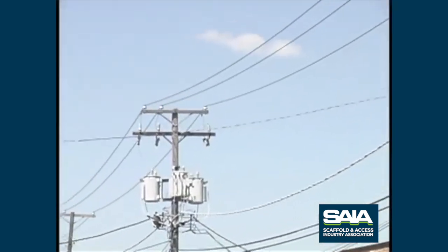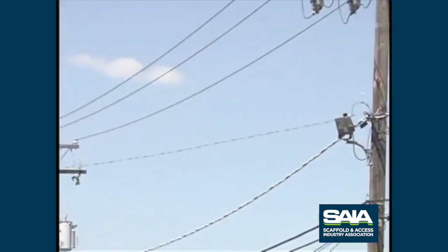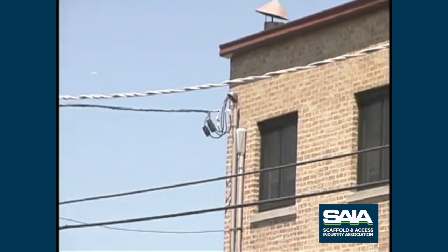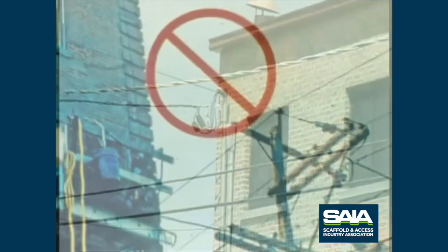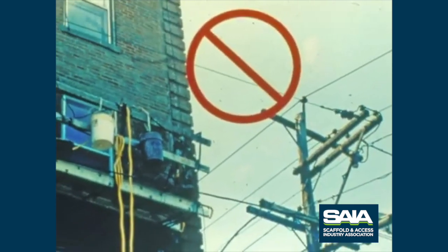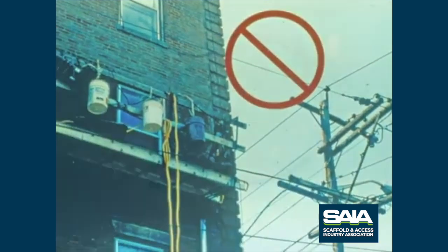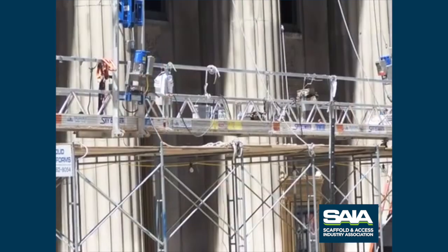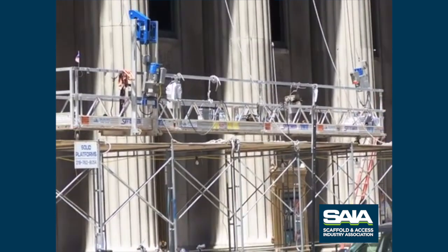Extreme caution should be taken when lowering ropes or operating the stage in the vicinity of exposed electrical wires. The hazard increases as the voltage rises. Consult your local power authority before commencing any work. The leading or better end of the rope must be long enough to reach the ground or lowest safe landing.